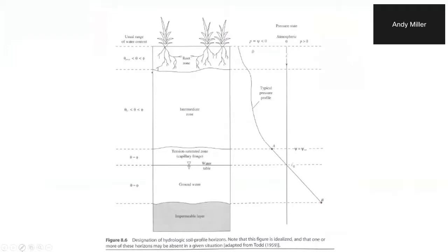So when you have positive pressure, then you're beneath the water table, right? So at the water table, again, what's the pressure at the water table? Should be 0, right? I mean, it's not actually 0, it's atmospheric pressure, but we basically set it equal to 0. We call that gauge pressure, and our datum is 0 because we're trying to exclude the effect of the atmosphere here. So 0 pressure here, positive pressure here. We all know that the pressure head is a function of the depth below. Well, it varies once you're dealing with a real aquifer, but in a column of water, certainly the pressure head is a direct function of the depth.